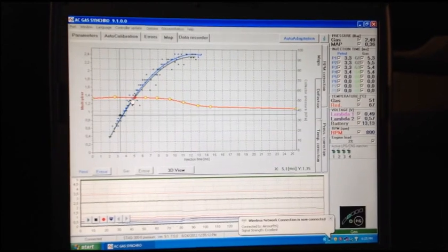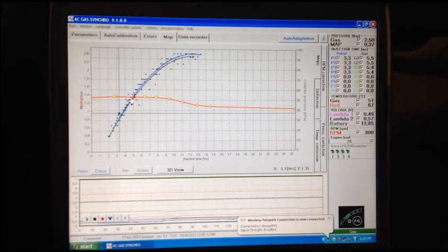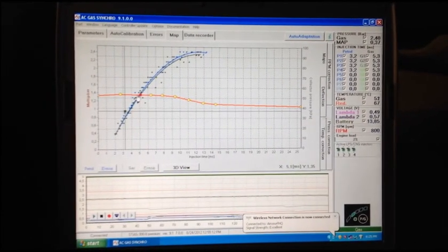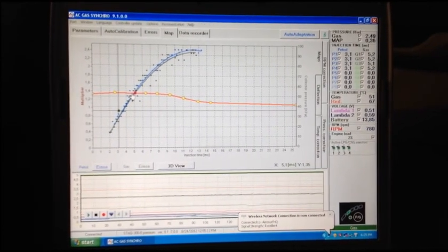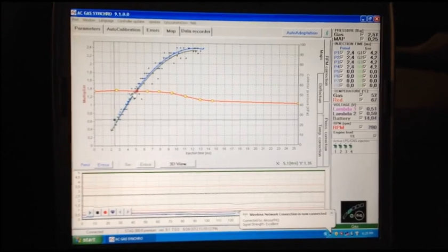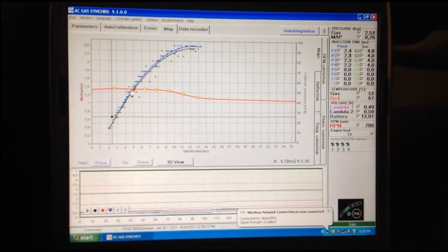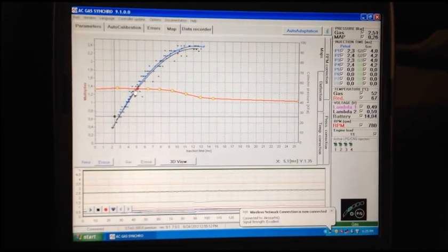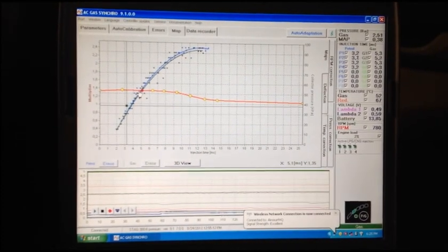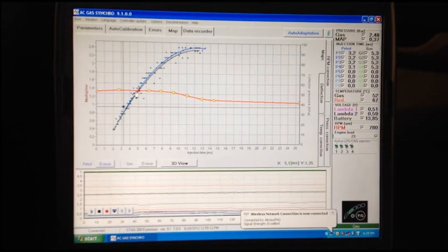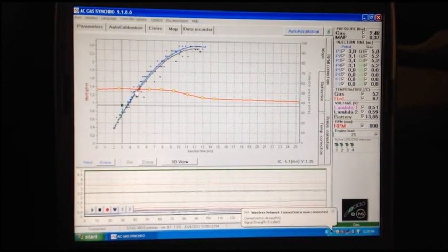Well, once it's ignoring the oxygen sensors, it's kind of your opportunity to lean it out just a little bit, and you'll get better high load, high RPM performance as long as it's not monitoring in that area. And the later model cars that do not go into open loop, you just want it to match up perfectly, because it's still making corrections. You know, you can go 10% up or down, it's still going to see it at the oxygen sensor and correct it. So you just want them to be perfect.